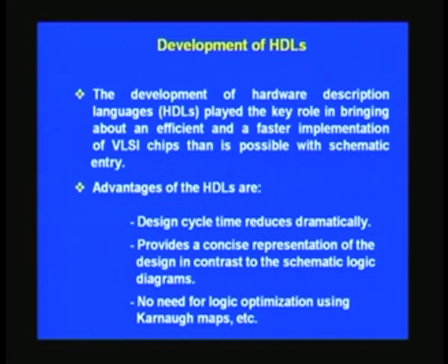Primarily HDLs were used in order to speed up design cycle time, and hitherto schematic circuit diagrams were used, and it was very handy for designers who had been accustomed to designing systems using discrete digital ICs, which you know, 74 series and so on.